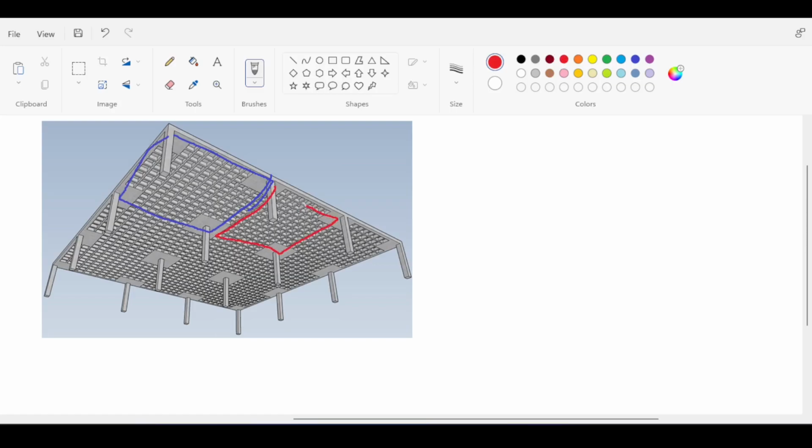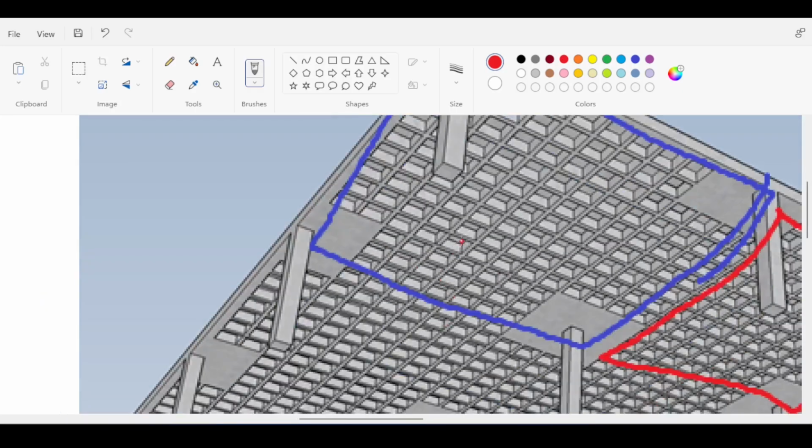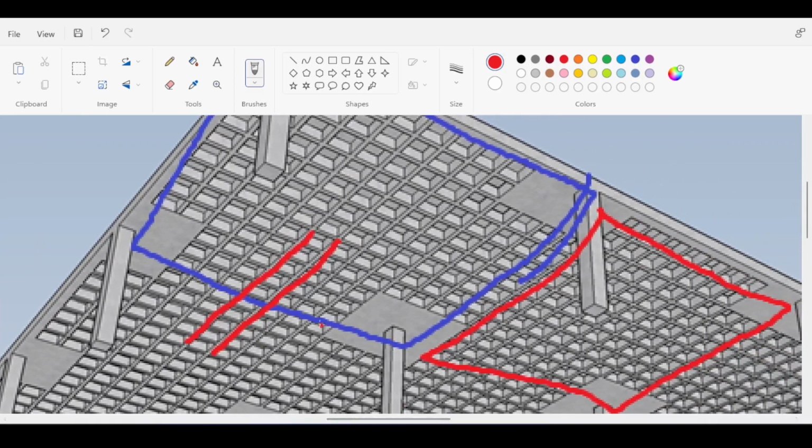And you notice something very important in those ribbed slabs. The continuity of a ribbed slab between a panel and the next panel is crucial, not only for practical reasons, but also for structural reasons, because the continuity of a rib causes the rib to be analyzed like a continuous beam, whereas if your rib is misaligned, then it becomes a one-span rib rather than a continuous rib.